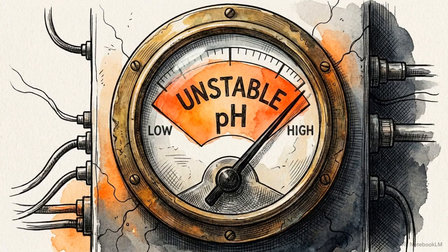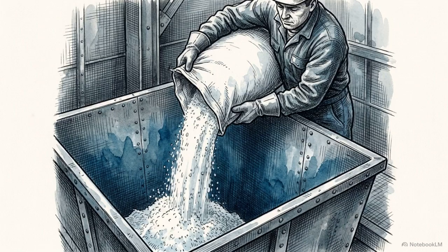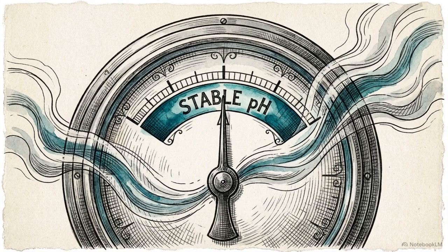However, this chemical environment is highly unstable. If the pH level drops, the cyanide rapidly degrades. To prevent this degradation, operators add lime to the mixture. The lime functions strictly as a protection alkali, chemically stabilizing the pH of the solution.